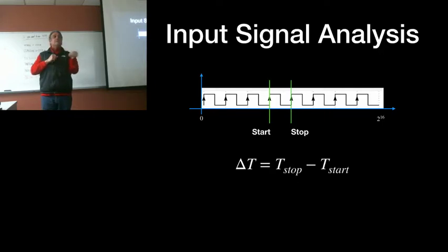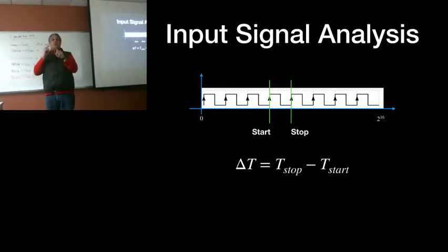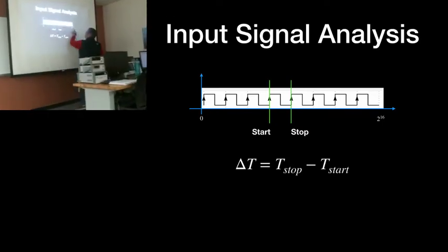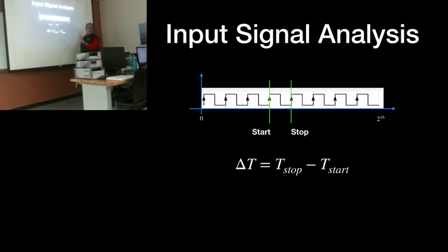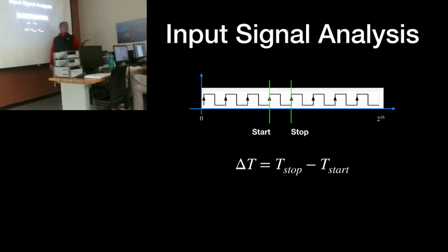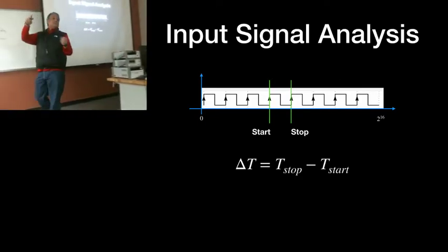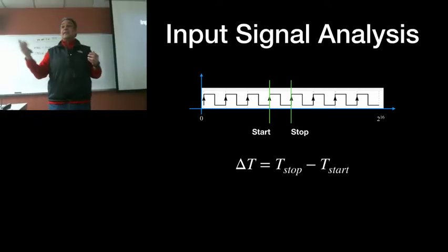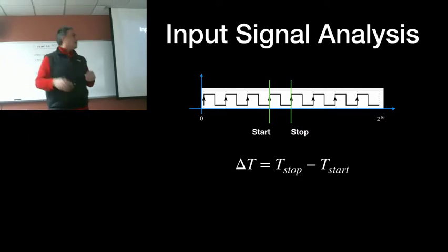But the only way you know that is that you know the clock overflows at 60. I go from 1 to 60, and then 1 to 60, and again. The only reason you know you did not travel back in time is that you are taking overflows into account. Now, time for a microprocessor is not given in seconds but in counts. Timer 1, which we studied last week, just takes a crystal, a pre-scaled version of it, and goes 1, 2, 3, 4, 5, 6, 7, 8, 9, 10. Just counts. That's all it does.